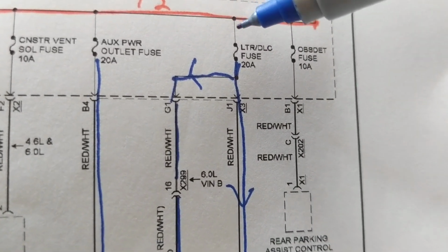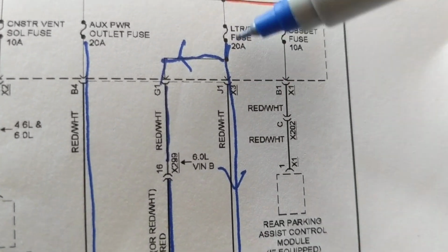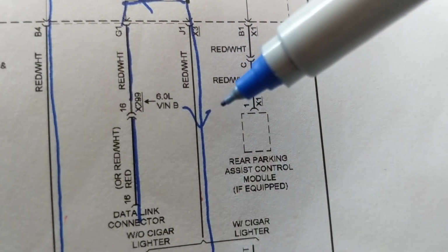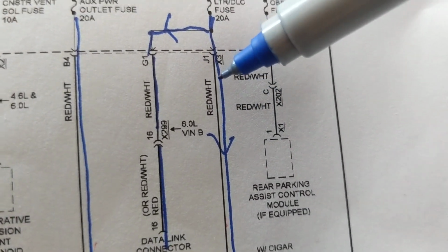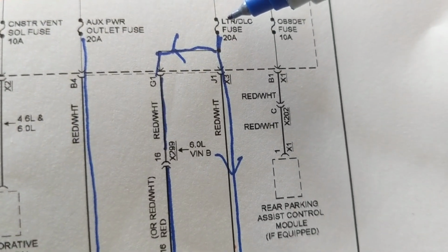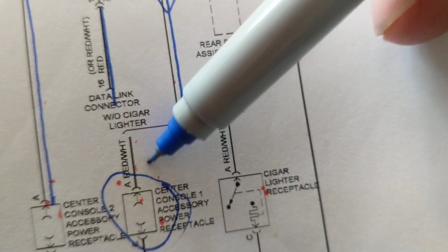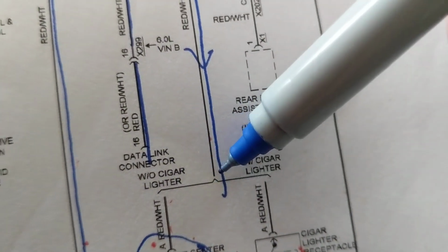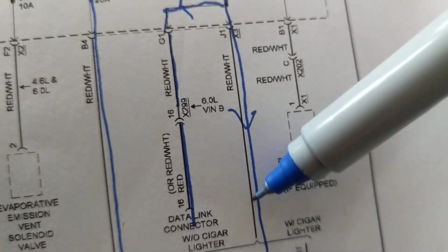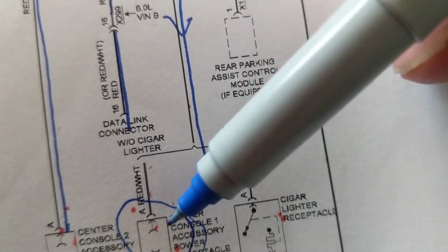But when we come to this point, if I want to know this fuse is good, what do I do without even measuring, without even putting a Fluke meter? This goes to the receptacle that we just said. I don't have 12 volts over here. I put it in my charger to charge my phone. Nothing. Fine, we know this is inactive.